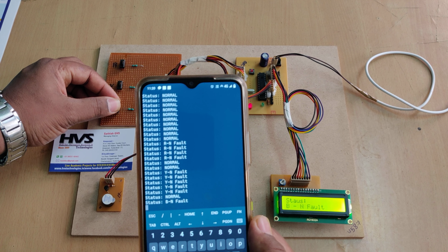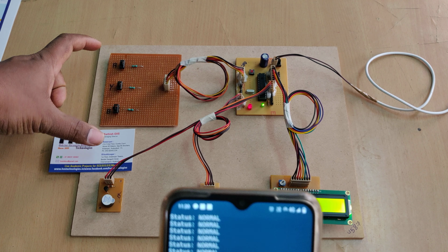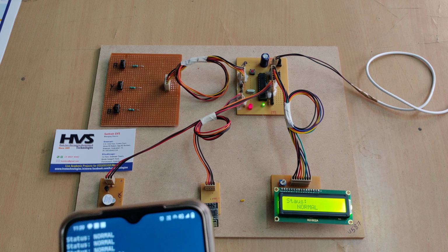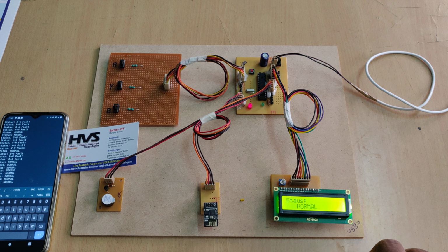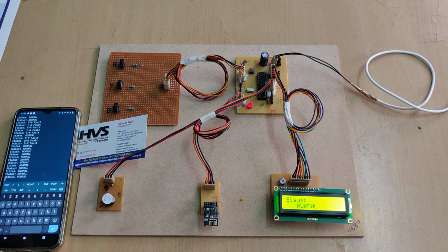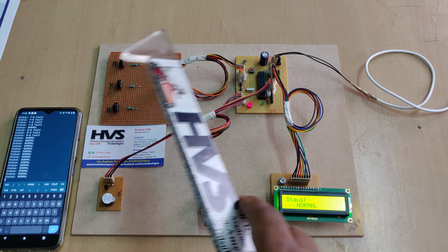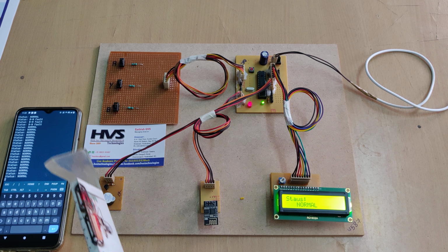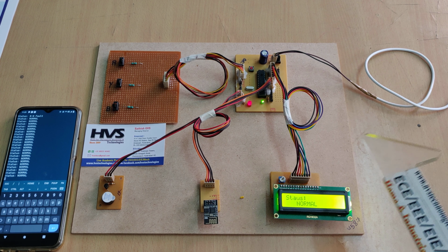And next, B to N. Here the switch connections are like this: this switch is given for the phase and neutral. Whenever we join this switch, the particular two pins are attached and the microcontroller will get 0 voltage. That is indicated as line to neutral, and the respective pin numbers are A0 for R, A1 for Y, and A2 for B. In this manner we are going to identify which phase has a line to neutral fault.